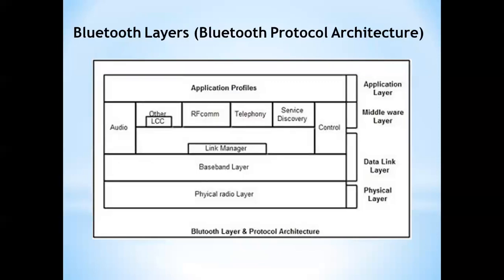Second is the baseband. The baseband is the physical layer of Bluetooth. It manages the physical channels and links. In addition to that, other services like error correction, data whitening, hop selection and Bluetooth security are also handled by this layer. The baseband lies on top of the Bluetooth radio layer in the Bluetooth stack. The baseband protocol is implemented as a link controller which works with the link manager for carrying out link level routines like link connection and power control.